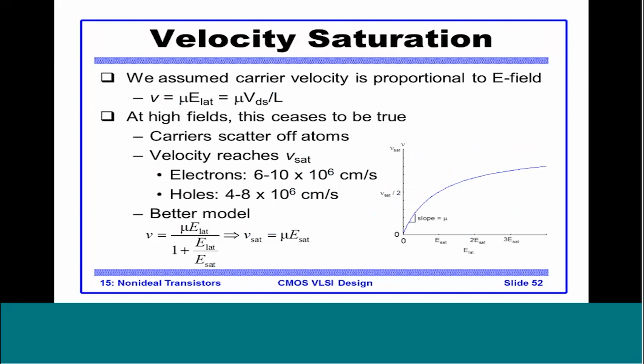So you can go back to your paper and see what if the L is, let's say, 180 nanometer and VDD is let's say 1.8 volt. How does that compare to L being 40 nanometer and VDD being, let's say, 1 volt? You would notice that the electric field strength has been growing. That is why we have to pull VDD down. Still the electric field is high enough to saturate the carrier velocity.